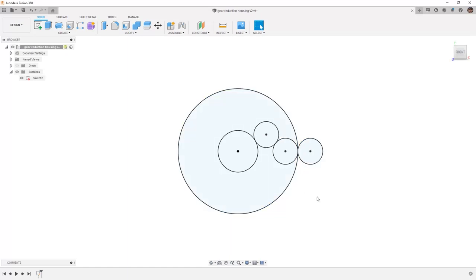So using this idler strategy and having 3 separate gears allows us to create the correct rotation of our input and our output. Remember that we are talking about our drive gear being our large gear and our driven gear being our small gear. But it is important to note that this type of assembly can work in either direction.